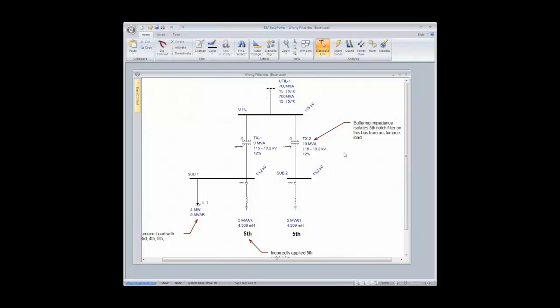Or what we also may want to be doing is applying power factor correction, and we want to avoid some type of resonant condition when we apply that power factor correction. So that's the two most key things that we're going to be applying notch harmonic filtering for: avoidance and for reduction in distortion. One of the most critical things, obviously, in a notch harmonic filter is its tuning.